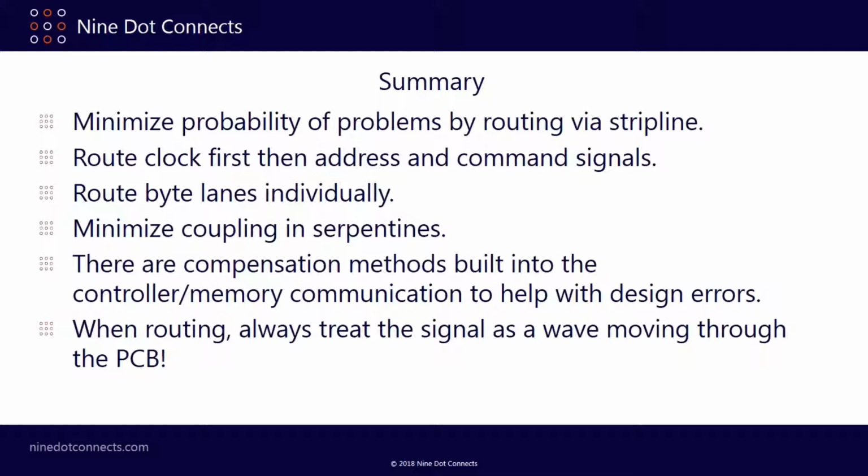Then there are compensation methods built into the controller and memory communication that can help with design errors, so you don't have to be perfect. When routing, always treat the signal as a wave moving through the PCB.